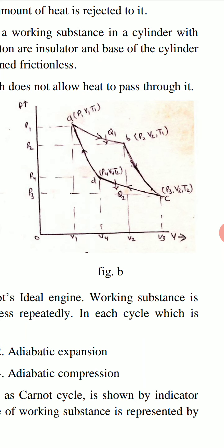So equation of state for adiabatic process for ideal gas is PV to the power gamma equal to constant, and from this equation of state we see that when the gas expands, volume increases from V2 to V3, its pressure decreases. Now it decreases much more sharply than that in isothermal expansion process.